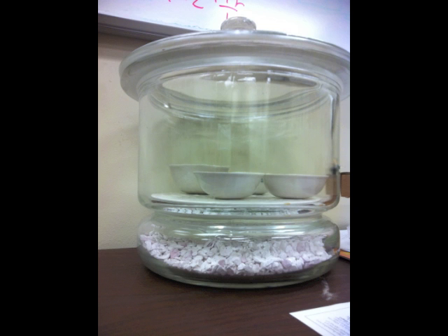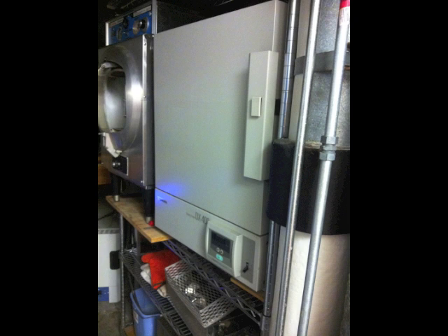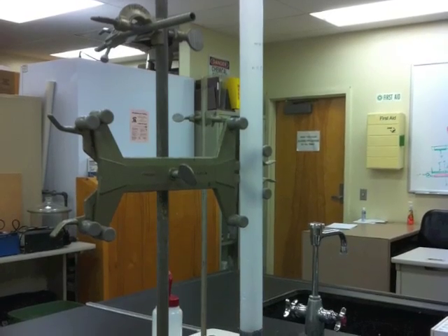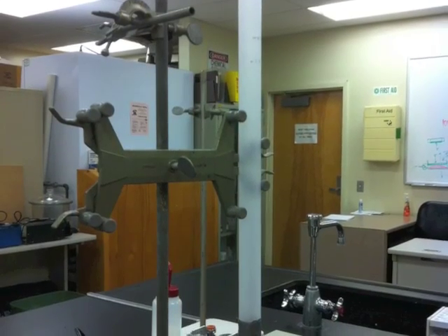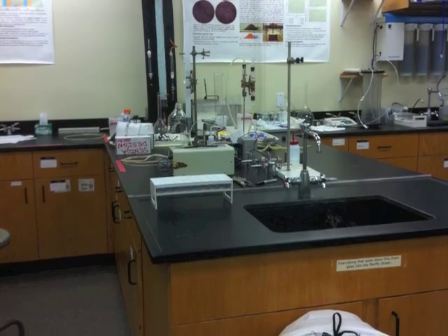There was a total alkalinity of 97.3 milligrams per liter as calcium carbonate and a total hardness of 129 milligrams per liter as calcium carbonate. Alkalinity and hardness were used to help estimate the concentration of ions that would be determined by the IC analysis. The IC analysis found a total of roughly 8 milliequivalents per liter of ions in the sample. The ion concentration will be used to size the unit.